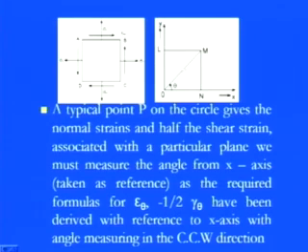We can simply put the analogy here: if we have the LMN and the shear strain, and there is no distortion, then we can simply get the O and ML, meaning this particular element is pretty simple. But if the distortion is there, and this L is moving towards L dash, or M is moving to M dash, or N is moving towards N dash, that means there is a distortion towards that direction. The shear strain components can always be measured with the distortion in the angle, and then we will check whether it is a positive or negative direction.